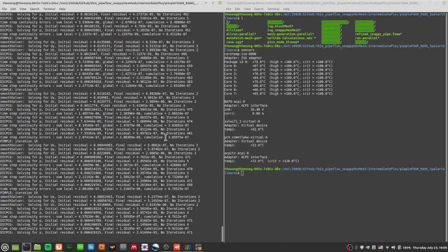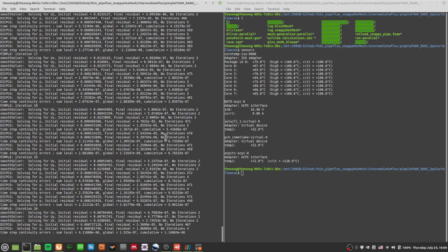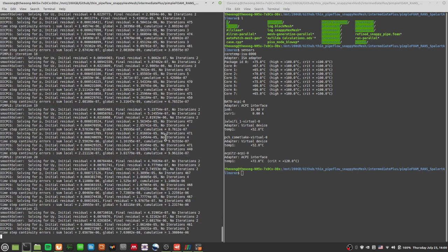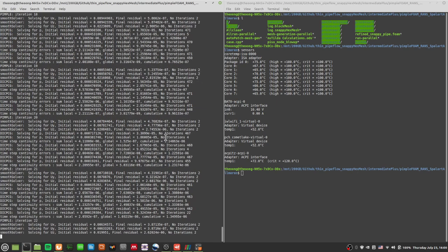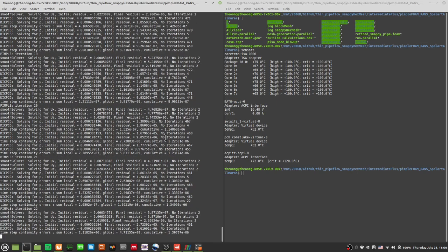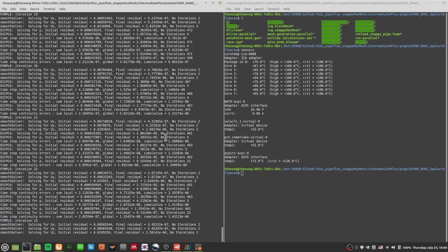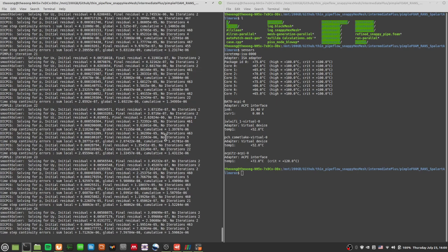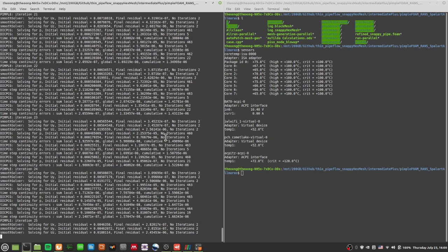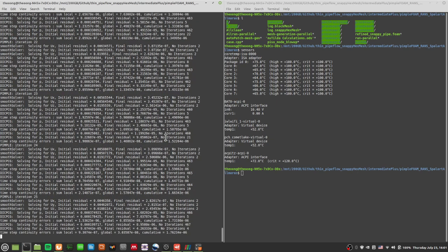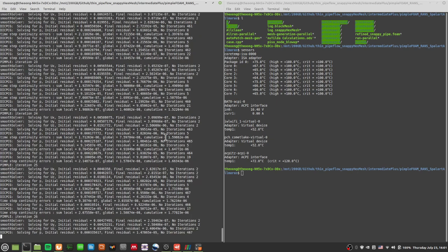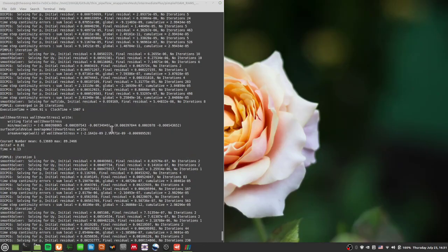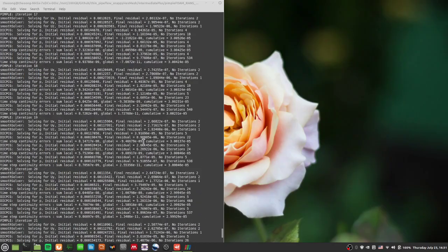And it's a lot slower than before because we decreased the relaxation factor, excuse me. Yes, you decrease the relaxation factor so that the solver can solve a little better. So it's decreasing reasonably well. And now I guess we can just do the fast forward. Okay, so yes, it has worked.